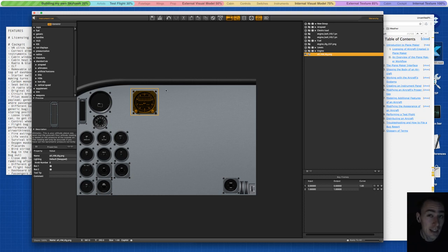And I think, but I'm not sure, it's actually weird. I remember him saying that, but at the same time it's a bit weird, because the reference speeds in the manuals are indicated airspeed, which makes sense because that's what the pilot is looking at. For example, the stall speed is indicated airspeed under standard conditions. So it makes sense to just look at the indicated airspeed and not the calibrated airspeed. But again, testing an airplane is also an art form on its own. So yeah, that's not going to be just a one-stream thing.